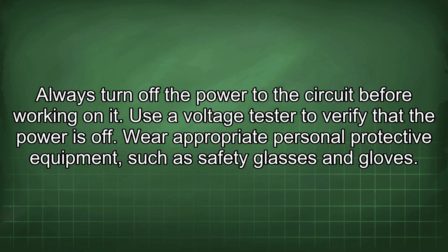Always turn off the power to the circuit before working on it. Use a voltage tester to verify that the power is off. Wear appropriate personal protective equipment, such as safety glasses and gloves.